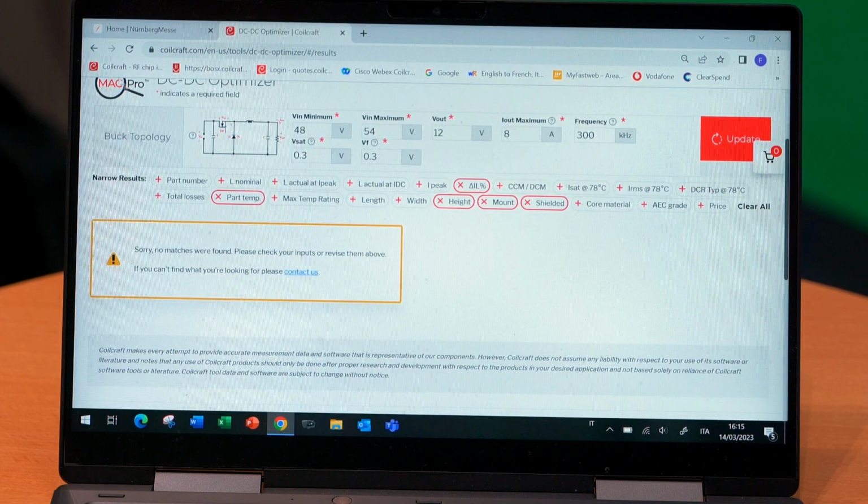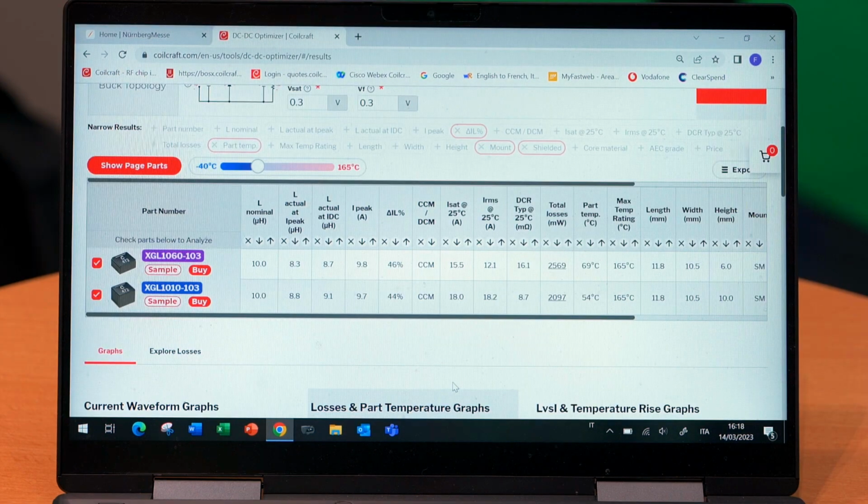That's an interesting exercise. This cursor here helps you to judge if this solution will still be good changing the ambient temperature. Of course, now we type a certain maximum temperature, like 75 degrees C. Moving higher, at around 70 degrees C, probably both parts will hit their maximum total operating temperature.